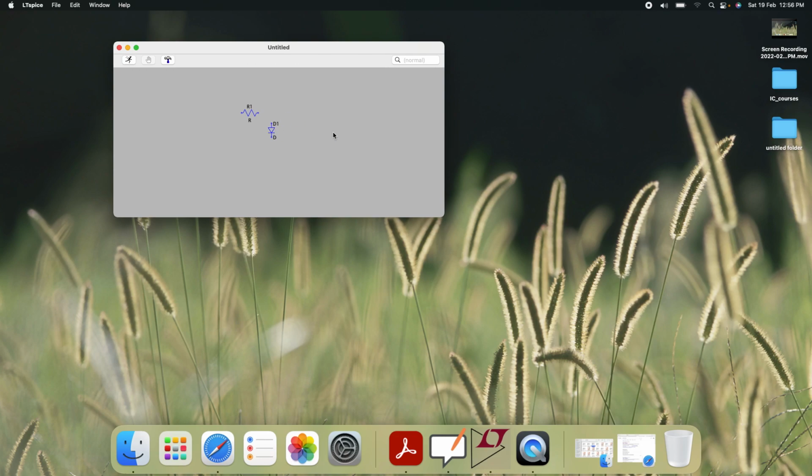Now I want to connect, and the next thing is the wire. If you are using it very frequently, then you will remember all the hotkeys. If you want to see which hotkeys, those are written over here. So F3 is for wires, F2 is for components, right? After a few days you will remember it. But let's assume that you don't remember the hotkey, which is F3, then wire is coming from Draft. Take it and just connect from one point to another point. So this is connected.